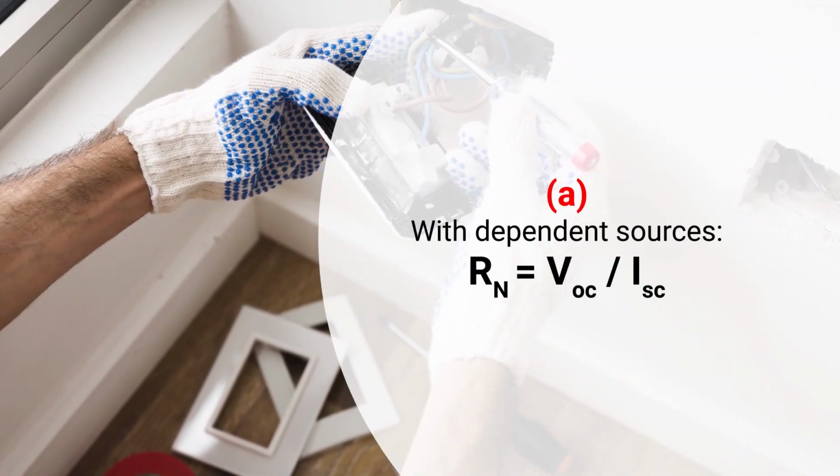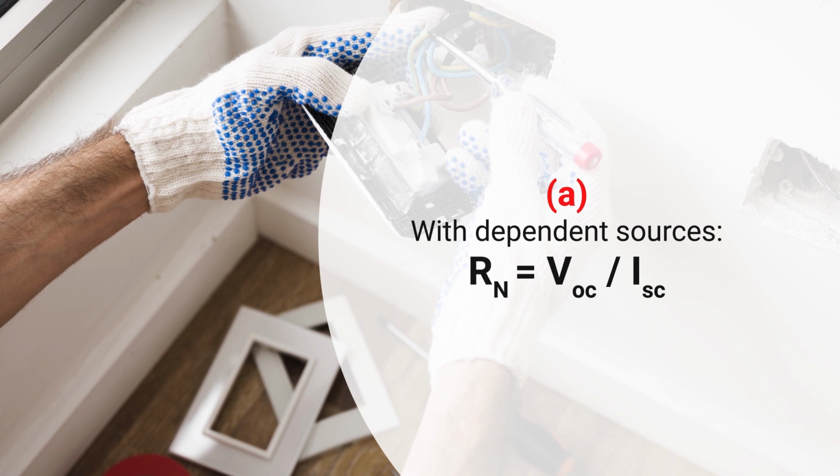So if there is a dependent source, then you have to find the Norton resistance by this formula. That means you have to calculate the open circuit voltage across the two terminals A and B. At the same time, you also have to calculate the short circuit current ISC, that is the Norton current. So just VOC divided by ISC will give you the value of the Norton resistance if there are dependent sources working in any circuit or network.